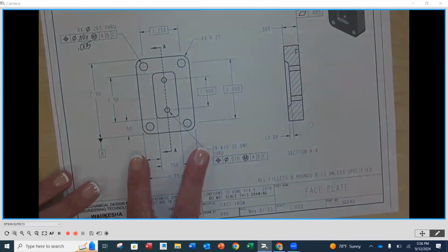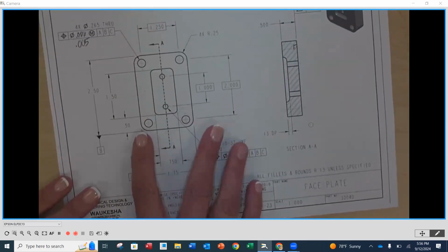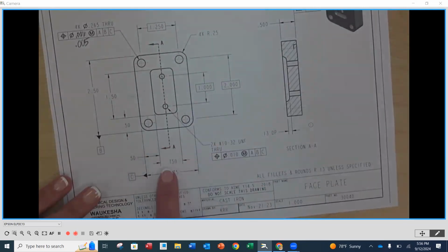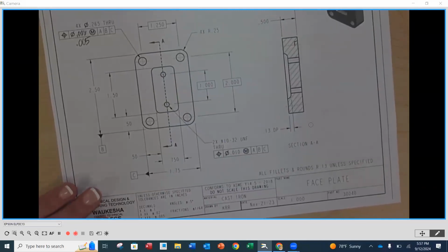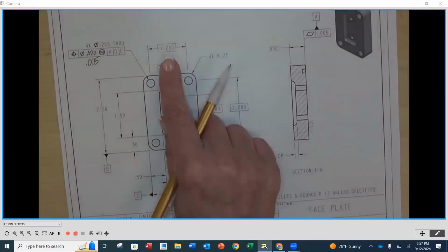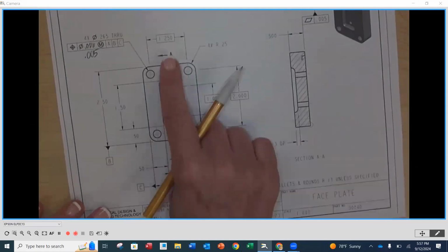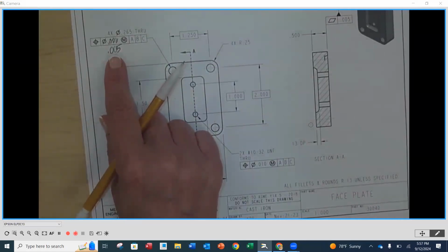Same thing for this orientation. We're going to find whatever that width is. Notice here that that's going to have plus or minus 20 thousandths on it. So whether it gets wider or not, it's going to depend on the center plane. And then from that center plane, evenly distribute that. Oh, no, I'm sorry, not 0.75. No, the 1.25, the basic dimension. You have to put basic dimensions on these locating dimensions. Have to. Because again, the tolerance is not coming from the title block for that. It's coming from our diameter of 5 thousandths at maximum material condition, then bonus tolerances and such for the sizes.